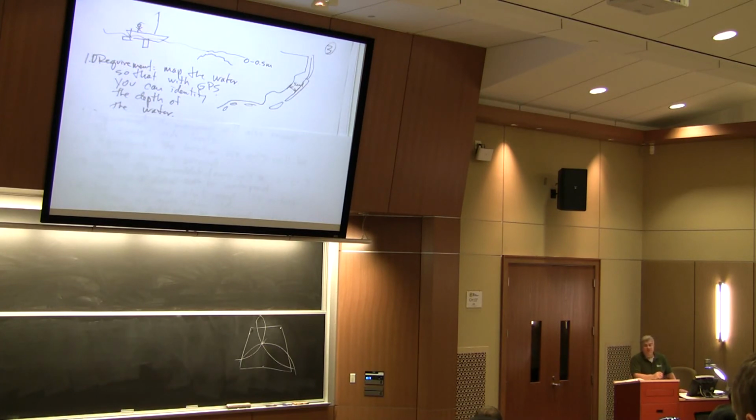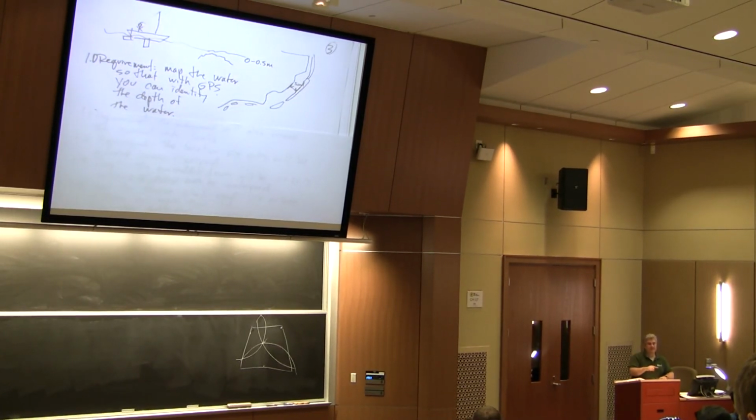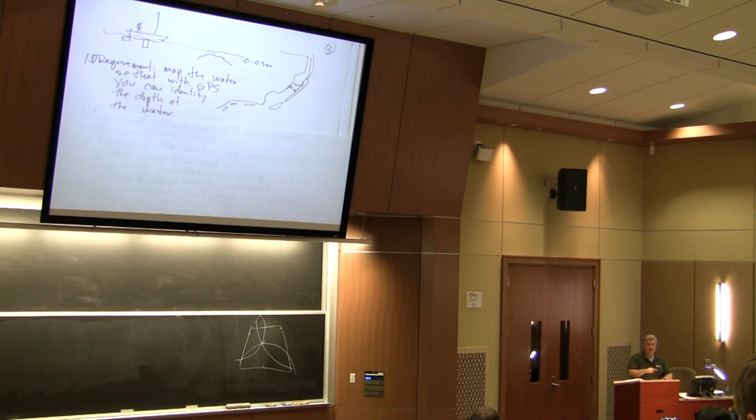Or, better yet, there may be some areas at high tide that are 1 meter deep, that at low tide are 6 inches, or about 10 centimeters deep. So it would be better to do it at high tide because you have a better chance of not scraping bottom as you measure. And then, of course, later on, you probably have to adjust for tides, right? You'll have to say, oh, if I'm sailing now in low tide, just subtract 1 meter off of all of these measurements, as an example.